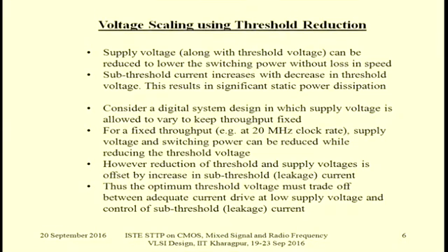You can question, only nanowatt is nothing. But remember that millions of transistors are there, so the sum total of all the devices from which this leakage power is drained will be a significant component of the leakage or static power.